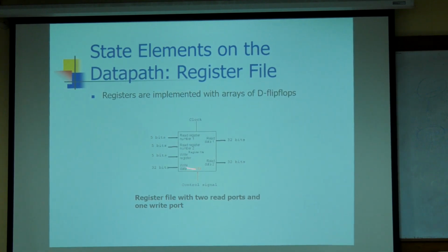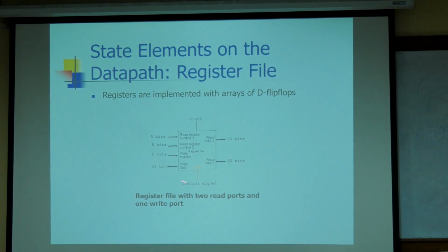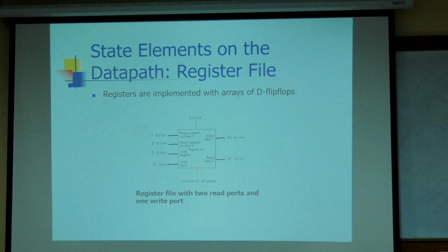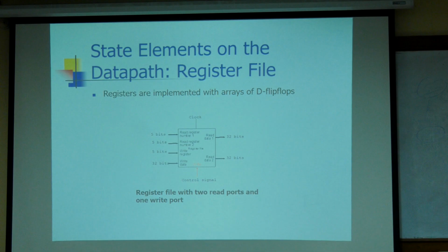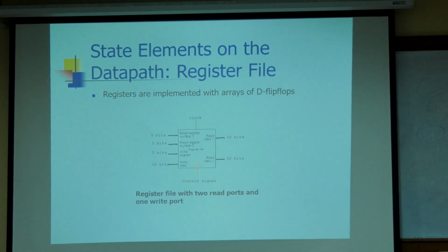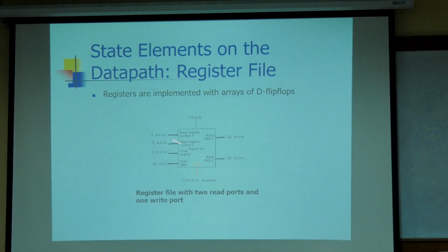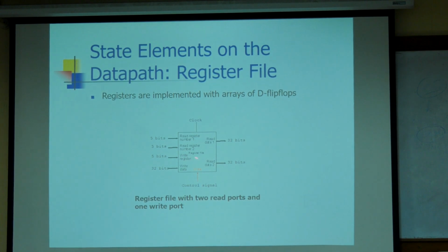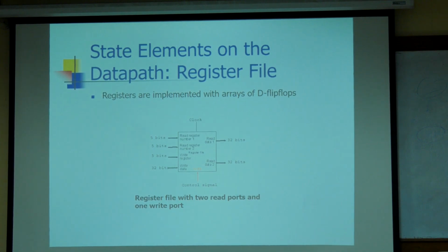We see this is the register file, the register file we are going to develop. It is required in the MIPS processor. So this register file internally contains how many registers? 32 registers, R0 to R31, each of 32 bits. For this register file, how many inputs are there? The inputs are read register number 1, read register number 2, write register and write data, and the outputs are read data 1 and read data 2. These are the ports of this register file.